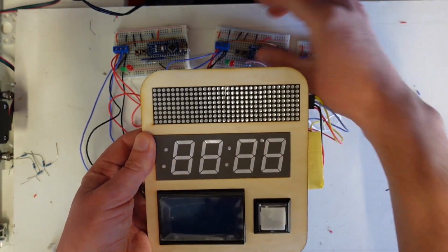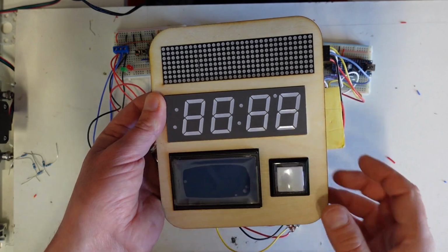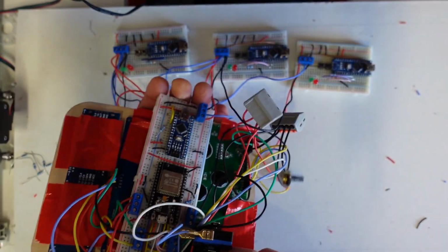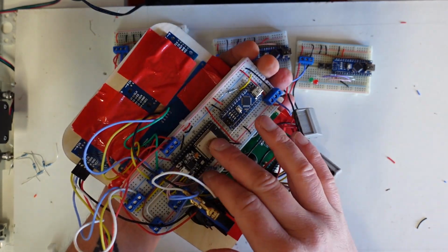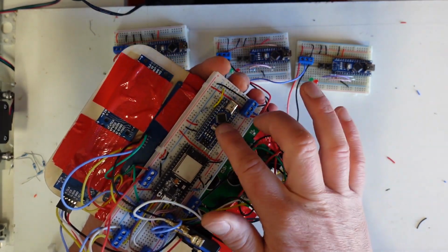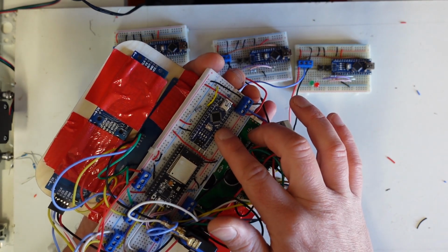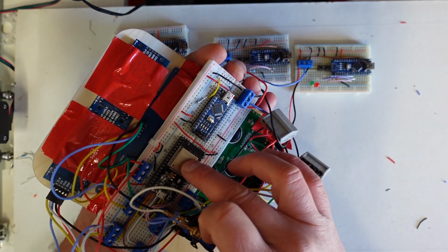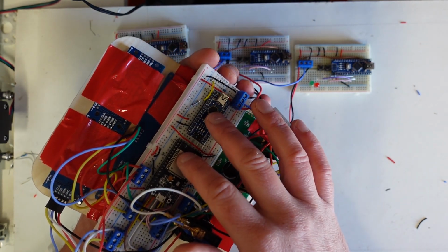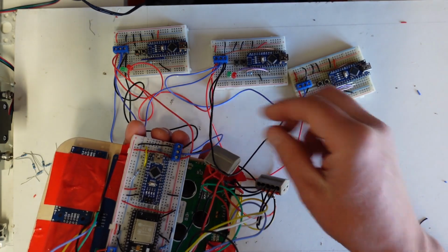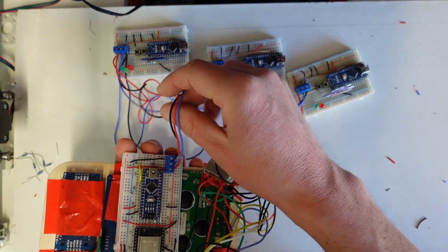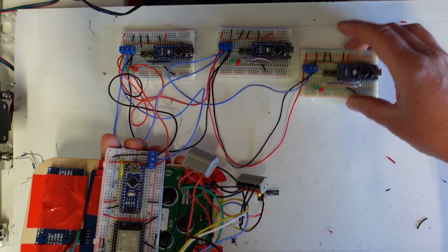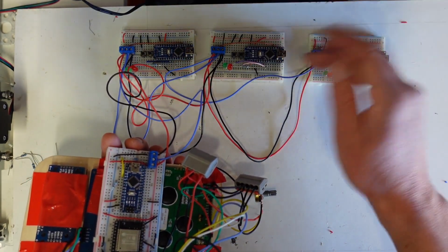So here's the hardware, and here's my master controller. The difference is now I've still got the same displays, I've still got the same button, and those are still connected to the ESP32, except I now also have a Nano on this board here. So these two are connected via a serial line, so the transmit and the receive lines of these two devices are connected. And then the Nano here is what is wired through these black and red and blue lines to the three slave controllers, which I've got in these Nanos at the top here.